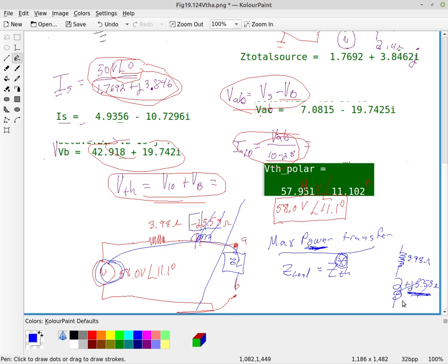All right, and that's kind of another way of saying resonance. When the impedance of the inductor equals the impedance of a capacitor, okay? I was drawing an inductor there to just say if you had an inductor there, but there was actually a capacitor here. Go back in the video and look at that. And so if you have a capacitor, you put in the load an inductor that matches that impedance.